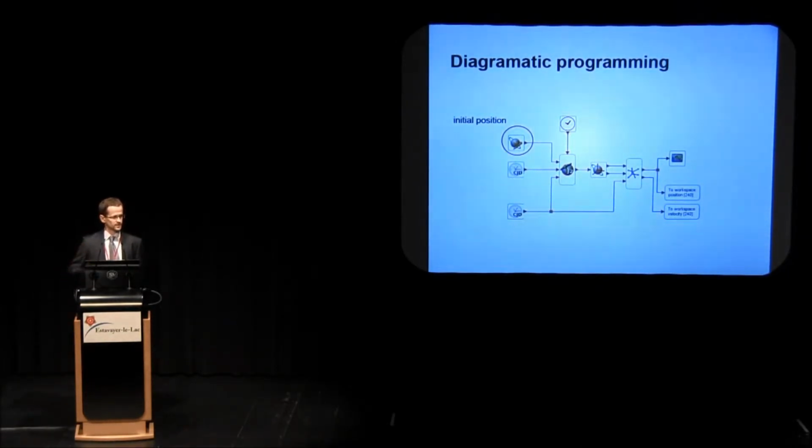First, to simulate a satellite orbit, you need to know the orbit in the beginning. This is done in many ways. Typically in this case, we are just giving it the Keplerian elements of the orbit at the initial time. We also have to say when the initial time is, so it's called the epoch. And we also have a block that allows us to configure how the time flows during the simulation.